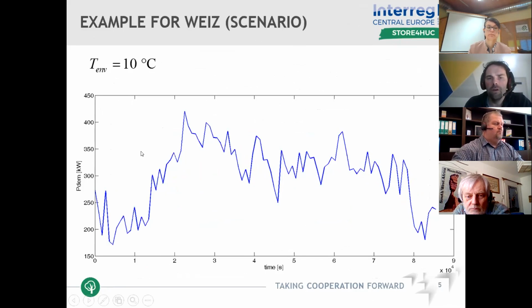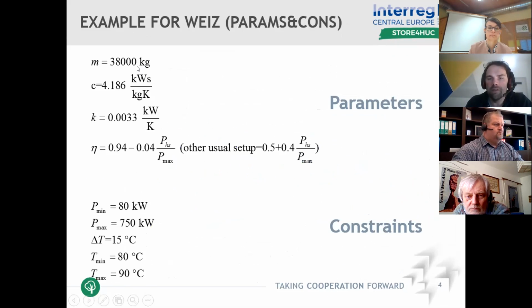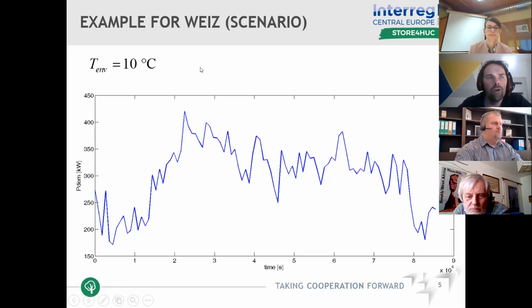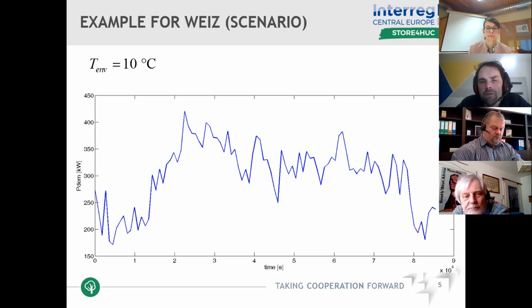With these two things, of course, considering that user has parameterized the module and entered all these parameters here, then he can use the module for different situations that occur on the site, and he can be advised how to run its heating system. But it's not online, so it's just computing advices for some time ahead. You, for instance, computed a day before for the next day, and then set up your timers based on it for turning on and off your heat sources.